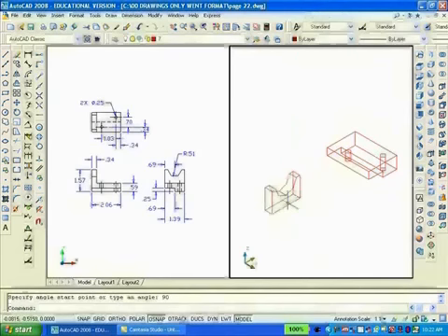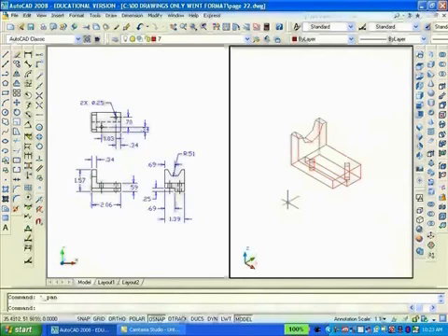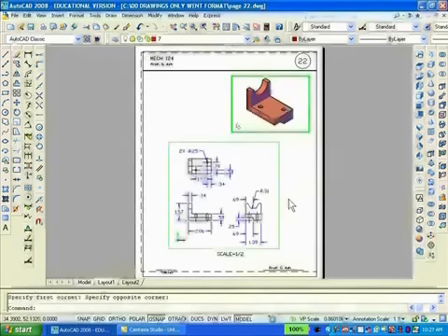And now I'll move that last part from its lower left-hand corner to the upper left-hand corner of the other part, and with the union command make all the parts into a single object. When that is done, I'll shade the object and the solid is complete. Then I'll set up the two viewports as desired in Paperspace, freeze the viewports layer, and this drawing will be completed.